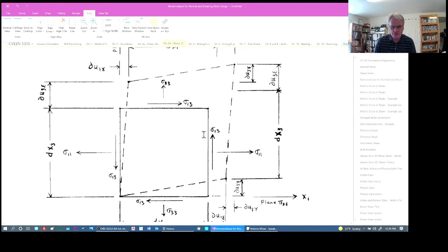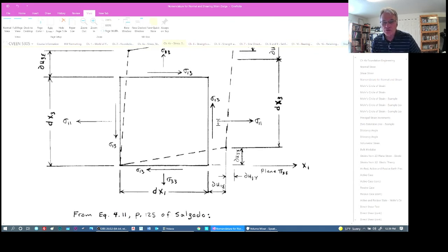And the shear stresses, he's used sigma also in his notation, where previously we used tau. So this would be, to us, tau acting on the x-plane in the y direction. So this is tau xy, and this would be tau yx in the previous discussion that we had in the previous chapter.